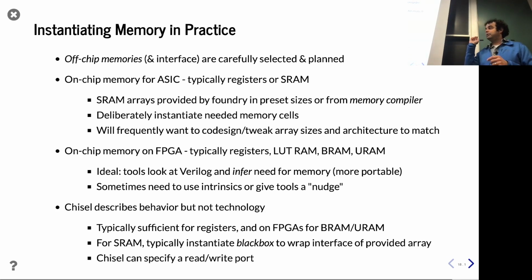Now make a 2-port SRAM. Compare the performance of the 2-port SRAM to 2 1-port SRAMs working in a banked configuration. See how that compares in terms of PPA. Depending on technology and the trade-off, you might be surprised which one is the better one. It's not clear from the outside which one's going to be more efficient. It's not guaranteed. So that's kind of that scenario.